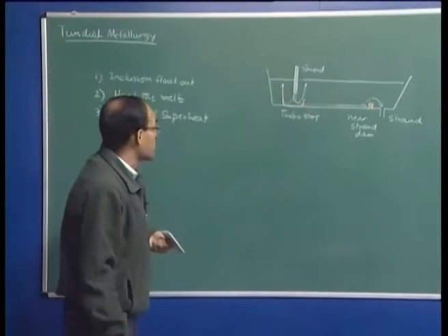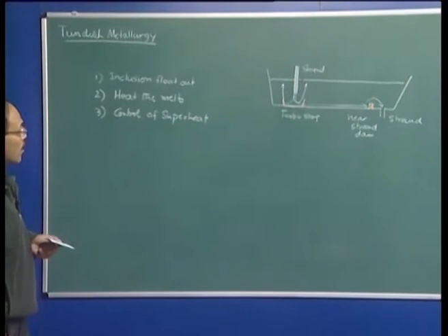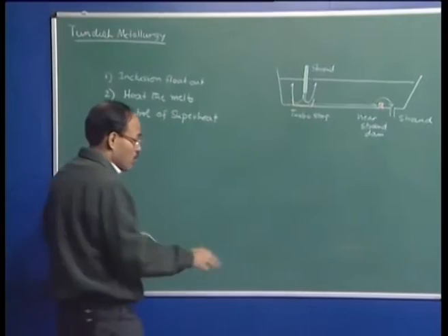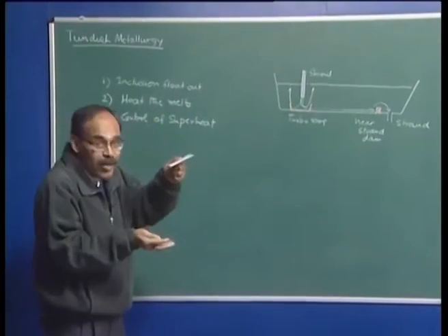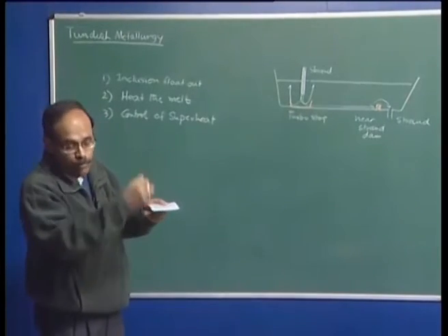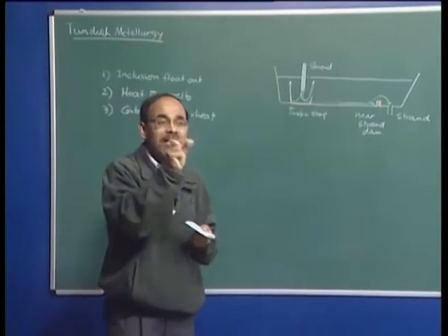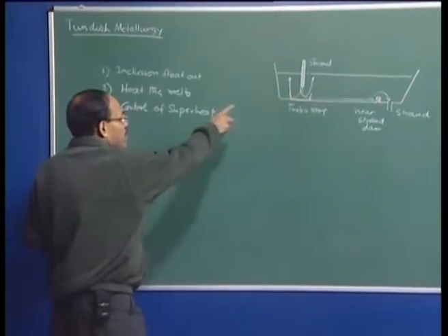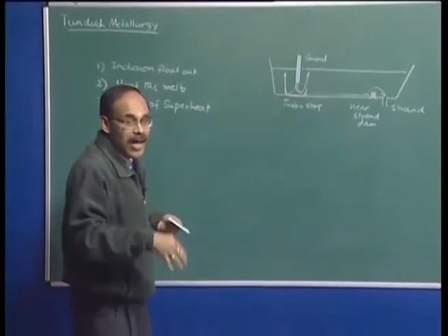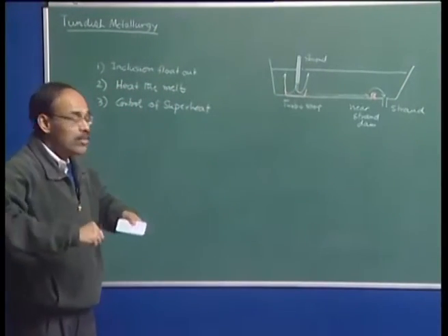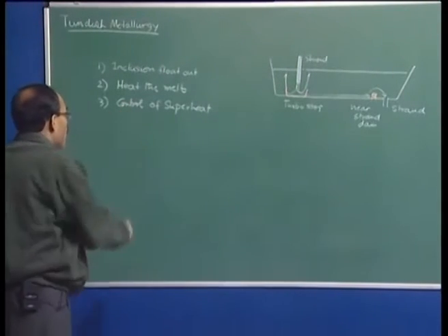The microstructure of the steel is controlled by superheat, and also it is not desirable to have a large superheat in the continuous casting tundish, because in that case you have to slow down the casting rate, because you would like to have some dwelling within the mold before the material flows out of the mold. Otherwise, what is going to happen? You are going to have a very thin shell. So, larger is the superheat in the tundish for a given condition in the mold, thinner is going to be the shell, and there is going to be more hydrostatic pressure on the wall of the solidifying billet. So, the superheat has to be very properly controlled.